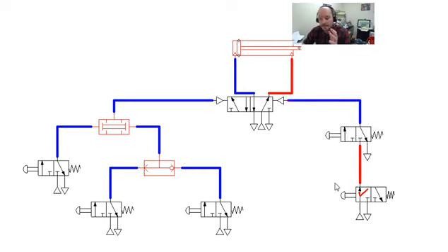And when it comes to pneumatic logic, although it's not used all the time, it is just as flexible as a digital circuit and a PLC circuit. And so these all can be done in motor control circuits, these type of logic circuits. Pneumatics are no different. So when you look at a motor control circuit, a PLC circuit, a digital logic circuit, all of those types of things can be done in a pneumatic circuit, and sometimes have to be, especially if you're in clean rooms where you can't have any electrical signals.